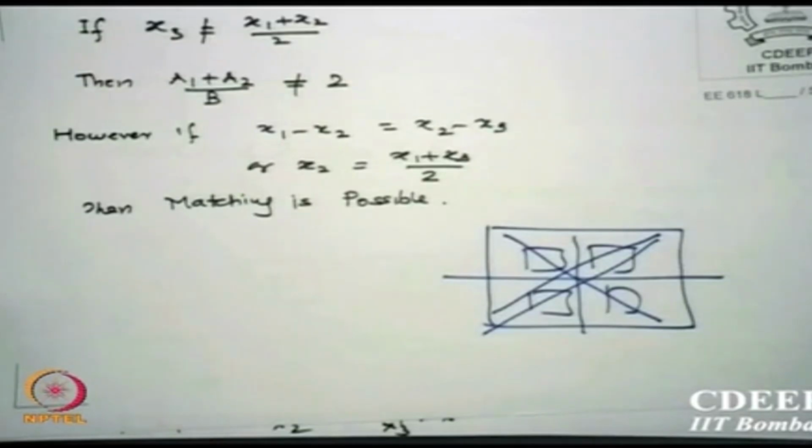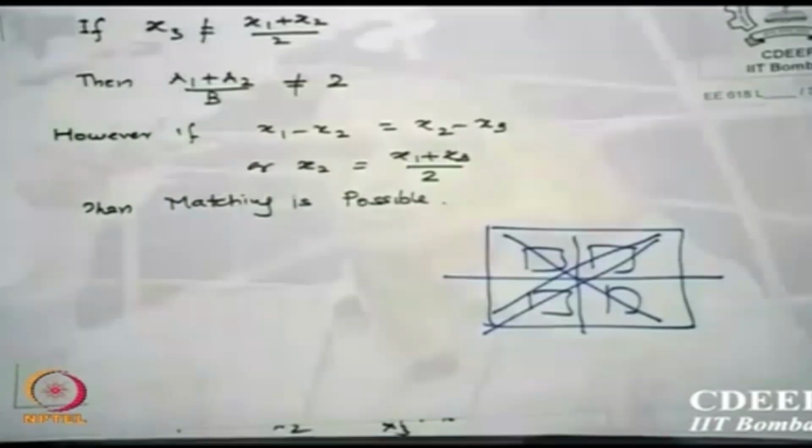So all analog designers should make their layout common centroid. So if it is 4W/L, then place two like this. So that, in a differential pair also you have two transistors, so M1, M2, M1/2, M2/2, M2/2, M1/2. Now you can see it is common to all four sides and therefore it will show minimum gradient effect.